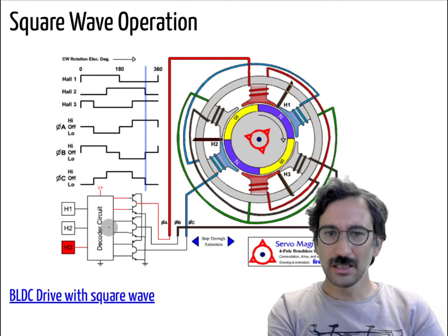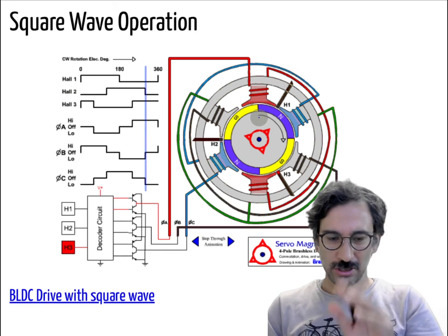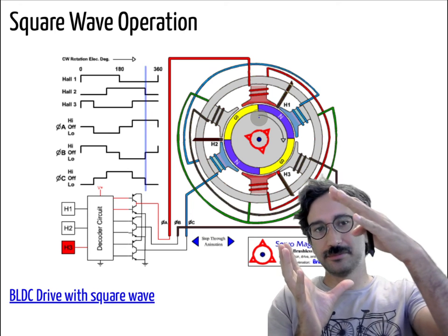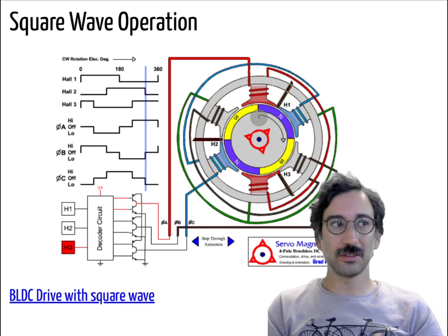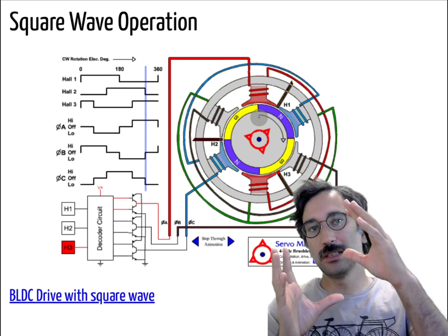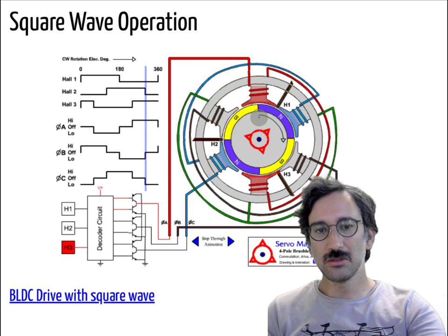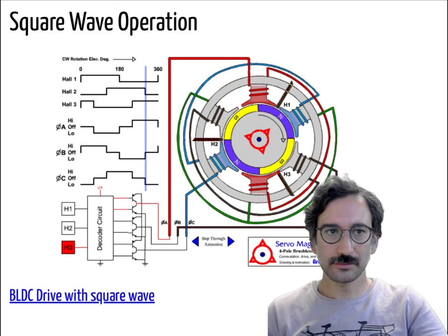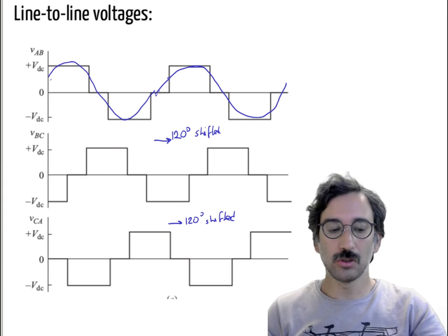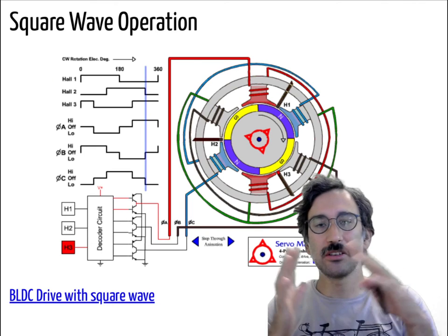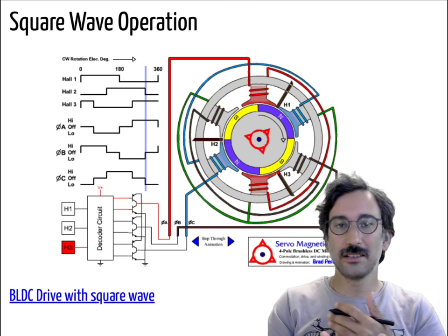There are also driver circuits for BLDC motors, and depending on the rotor position, because in synchronous machines you want to keep the load angle at some specific position, you fire those transistors with respect to rotor position. So it doesn't have to be constant frequency, constant magnitude; the frequency can be changed if you want to accelerate your motor, decelerate your motor, and so on.